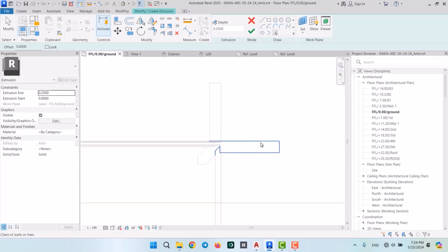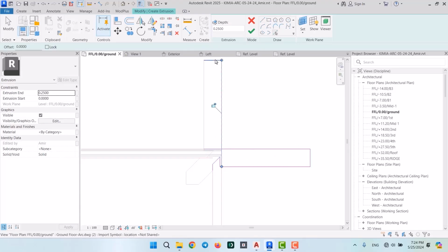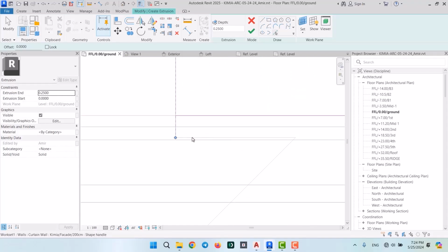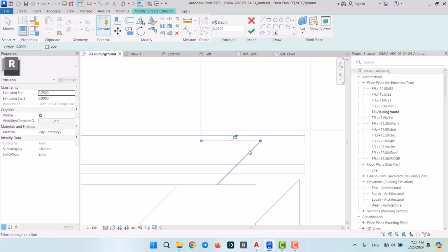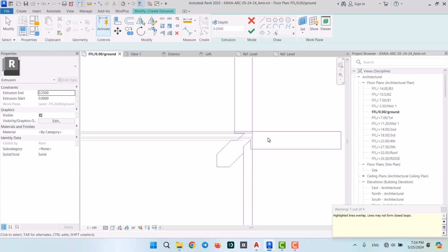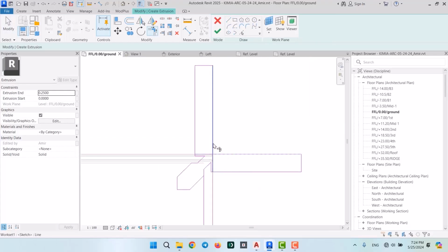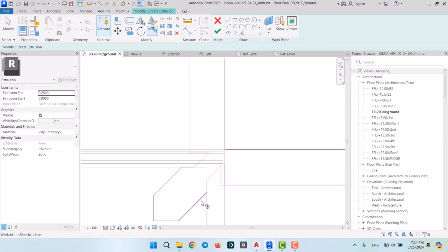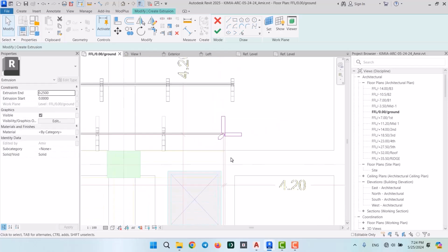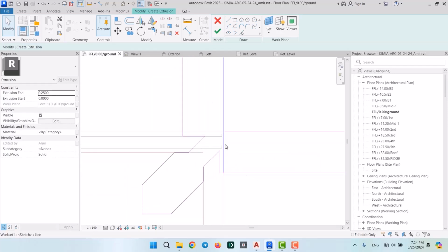So we drew an extruded item, we used pick line, and then we selected or picked the lines, and then we used extrusion. Let me select or pick the other lines as well, and then I'm going to continue. So this one needs to go over here, and this line right here is extra, as well as the one next to it.